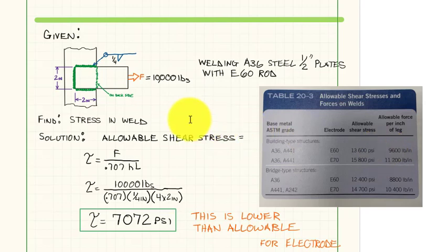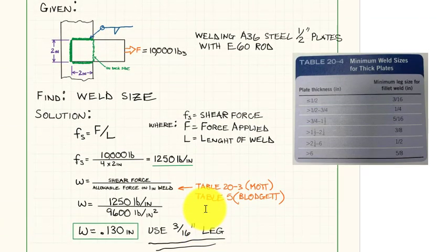So from this, what we're going to be doing in lab is we're going to be welding some coupons, putting some load on there, putting the weld in shear stress, and you guys are going to have to do some basic calculations of force and stress. You may have to do a little algebra here, but these are the basic equations. Again, not really that hard to size the weld for this. And talking about sizing the weld, if we were given this problem and looked at it from a different angle and said, hey, size the weld.